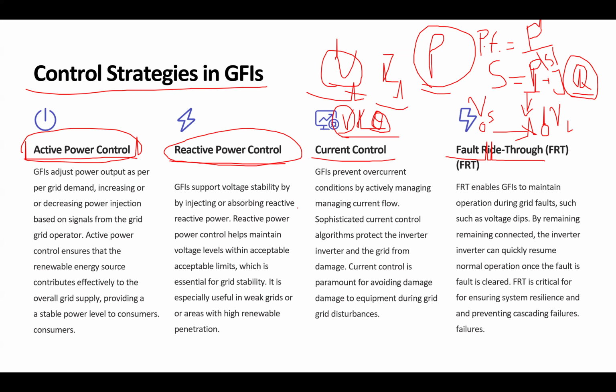And then we could say, okay, if we set these two phase angles properly, we could manage the amount of power that goes through the switching device, through the inverters, to the terminal. The same goes for the reactive power, by applying control over the amplitude of the voltage.